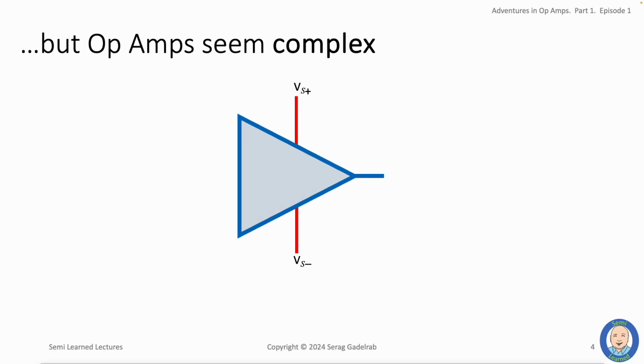To start with, instead of having a single input for our faint signal, the op-amp seems to have 2 input signals and not 1. They are both called V sub I, implying that they both can be used for inputs. But the plus and minus signs attached to them imply that we need a positive and negative signal as inputs to the amplifier. This begs the common question of how should we connect the incoming faint input signal to the op-amp?